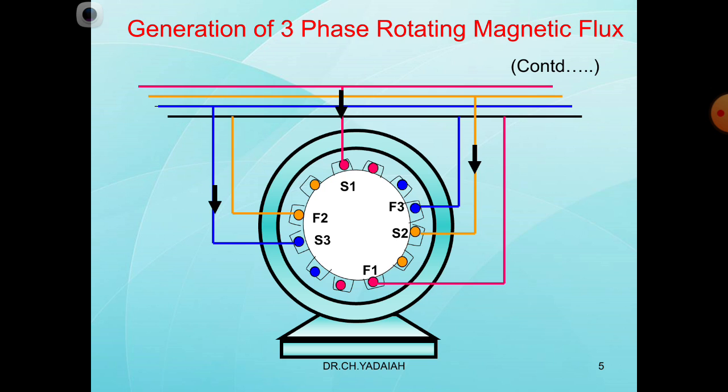Now this is a distributed winding. You can see here the R phase, B phase and Y phase at different angles, you can say RYB distributed. Each winding, as we know, has a starting end and a finishing end. The R phase is connected to the R phase supply at S1 and has two coils nearby.